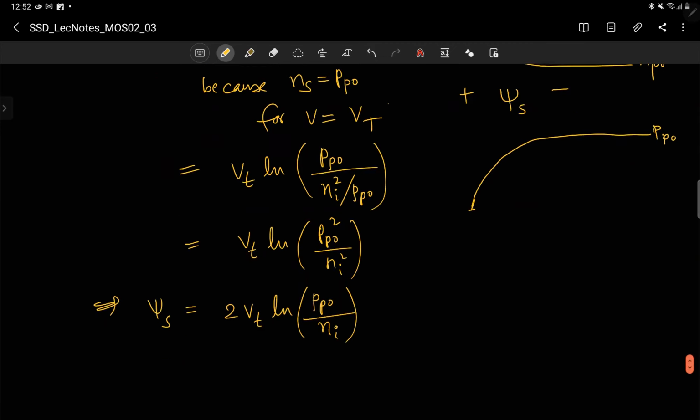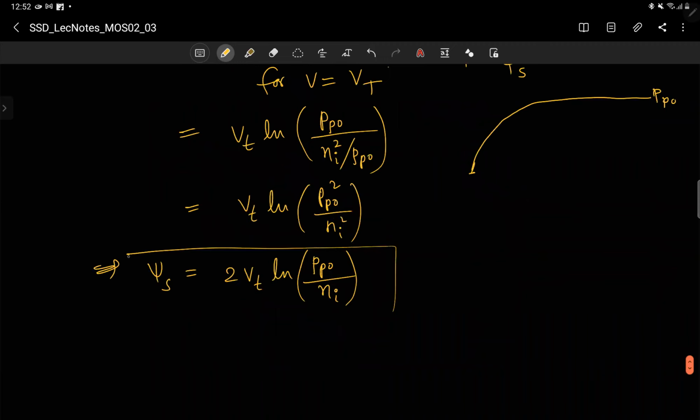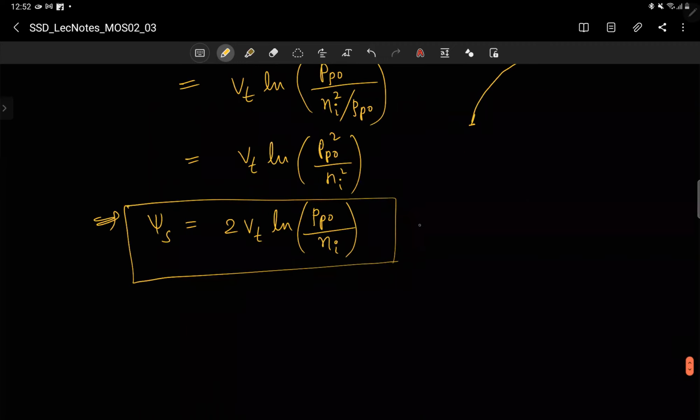Okay. So this is the semiconductor potential difference, and this must be equal to the area under the triangle, half times height into base. Height is Es, xd is the depletion width.